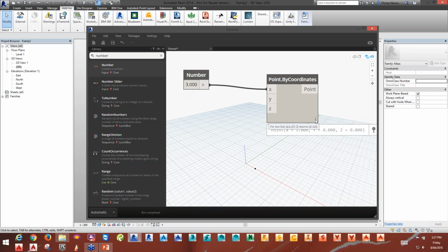When I click now on my point, I see obviously we create a point in X3, 0, 0. And we saw that the point actually did move. If I want to release this node, I can just click again and maybe connect it somewhere else, and we see that the point now moved into the Y. So if you follow this exercise and you have never touched Dynamo, you have the first cool schematic here, and hopefully you want to go wide. What we can also do is connect it to all 3 if you wanted to. And this means that we have in 3, 3, 3 our point.